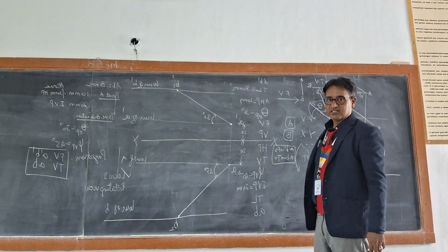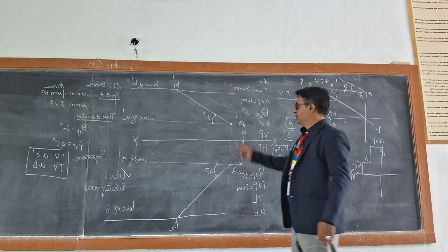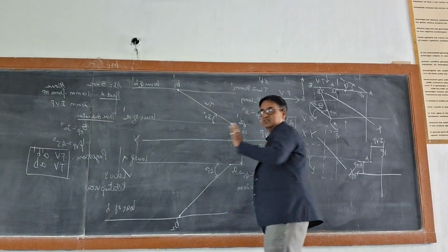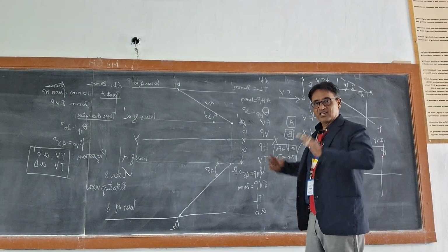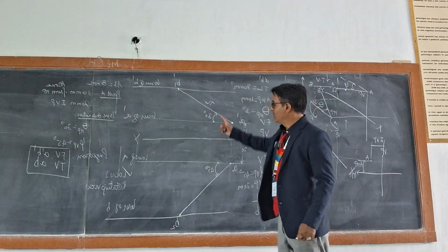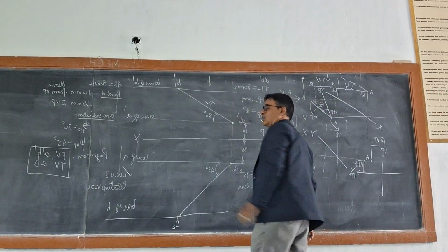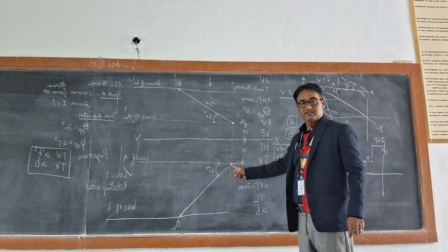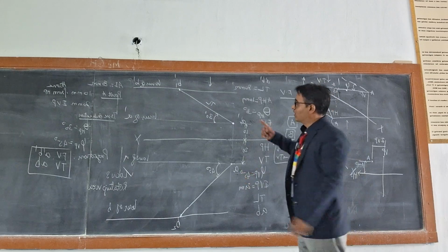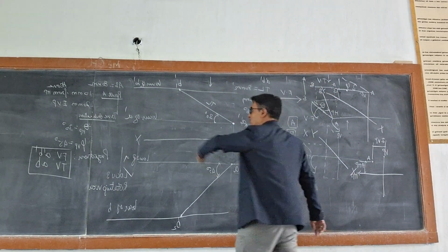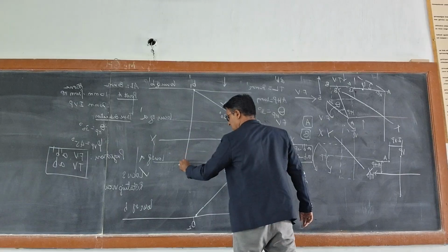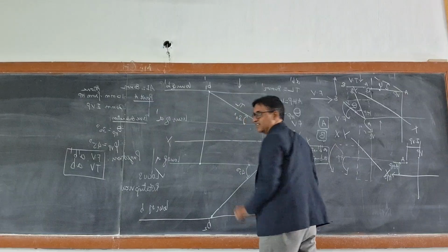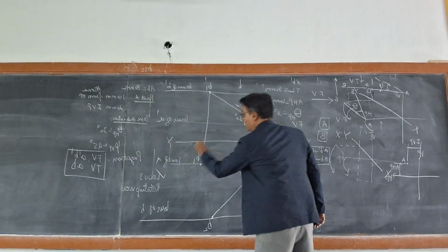And after this what I am going to do is, say for example, this is my actual line which is measuring 80 mm, true length, actual length. Okay, there is no reduction or enlargement of the length. It's a true length. Now when I am looking at this line from the top, what will happen? This point will be projected. Already we have got A. And what about B1 dash? That will fall down. It will be projected. And on this locus of A, you will be getting an intersection point which you call B1.